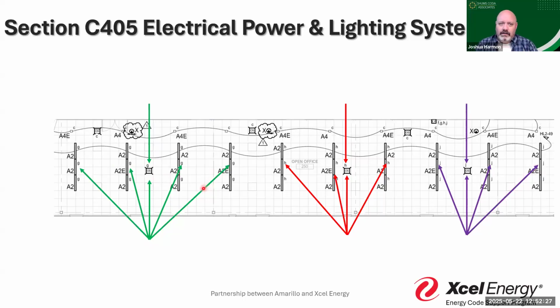I don't spend 6 hours doing lighting control for energy compliance. If I'm on it for 40, 45 minutes, that's normally more than enough time to figure out: did you calculate the lighting allowances? Did you have the right number of fixtures to demonstrate compliance with that lighting allowance? And then what am I seeing for controls and the location of those controls?